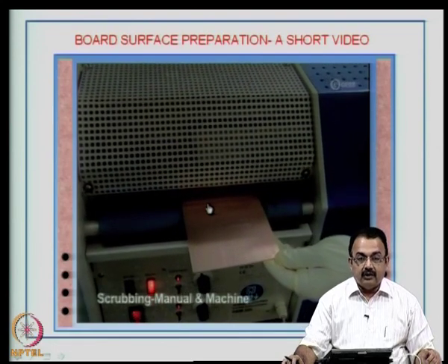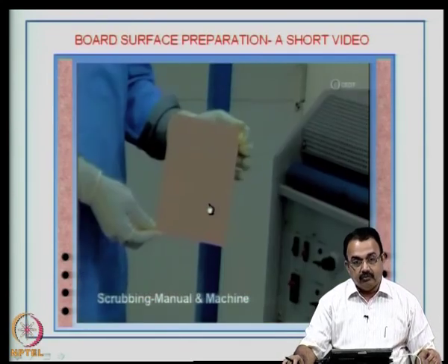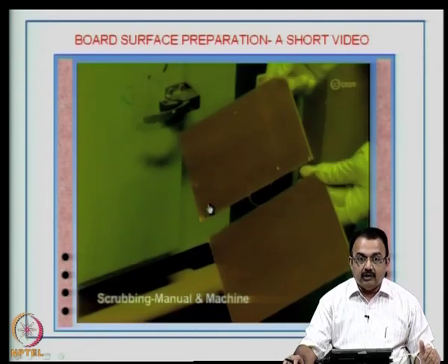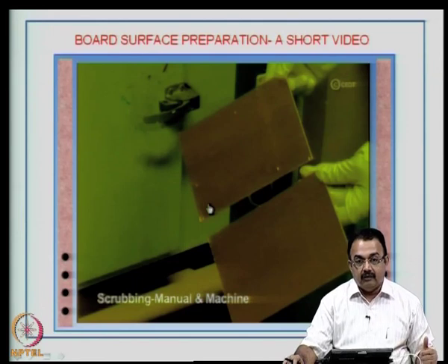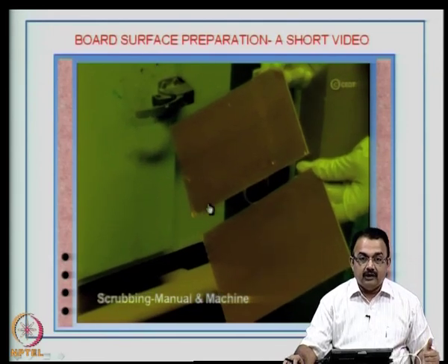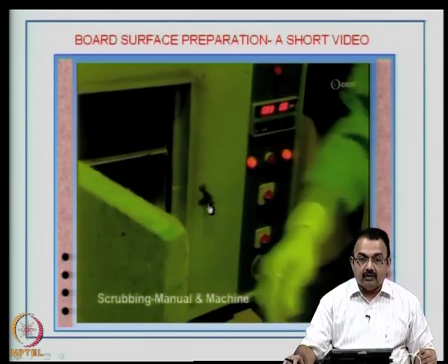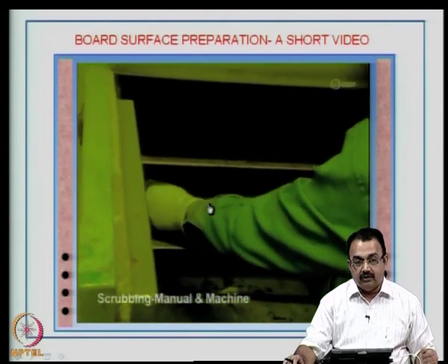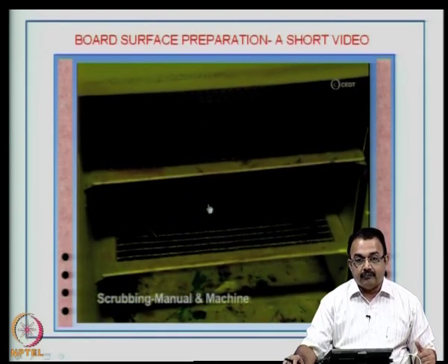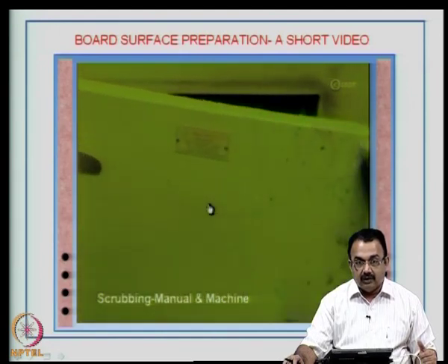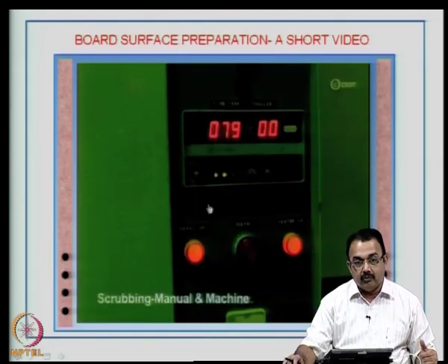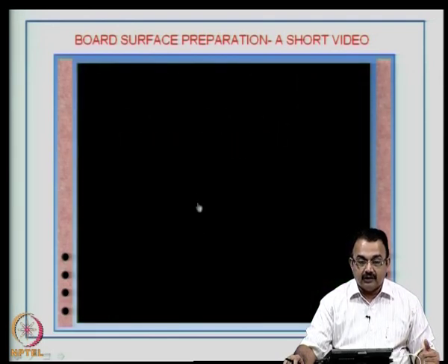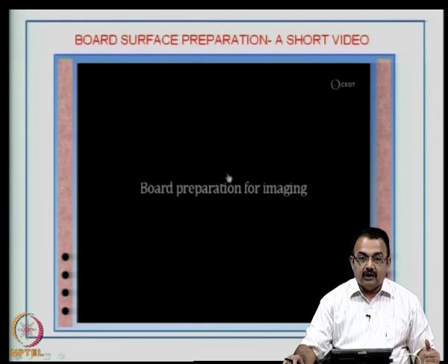Sometimes you can use a jet slurry containing pumice. Okay. You can use water mixed with the pumice material, and then you can form a slurry, and this slurry can be sprayed from the top and bottom of the brushing machine. Then you have the abrasive rollers. Together it forms a very nice methodology for scrubbing and cleaning your copper clad laminate, providing a larger surface area, removing the oxides and so on.